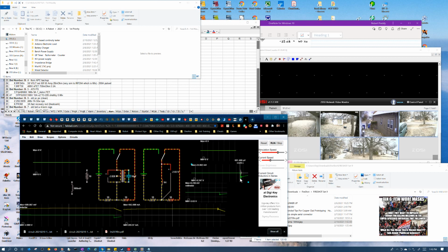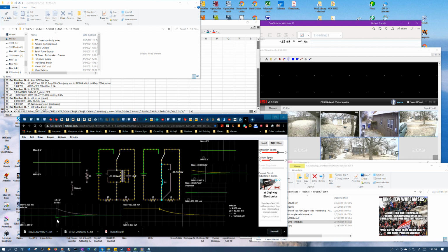Okay, so right now you're seeing a real quick and dirty oscillation here, but it's falling off really quick. It's not resonating or acting like a tank circuit as much as it did. That's because we've got such a low impedance now, it actually quickly dampens that oscillation. Even though the higher impedance produced a much higher voltage, you can see here that the voltages aren't nearly as high. Even this only has a maximum of -5 volts.